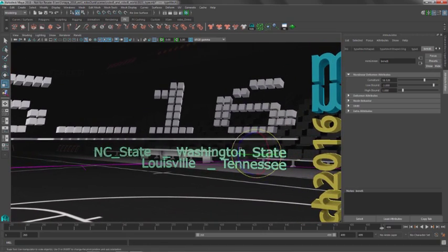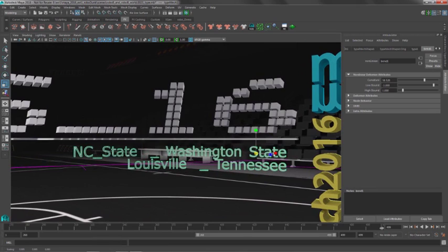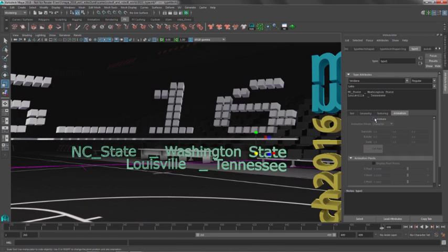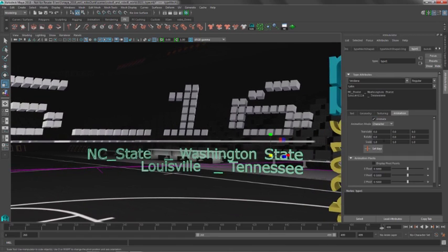And this is actually really pretty awesome. This is where the tool really starts to shine. If we jump over to the animation section and we turn on animate, we can animate any of the translation attributes. If we just start to spin this around, maybe the y-axis here, you can see that we're spinning essentially around the midpoint of each character.